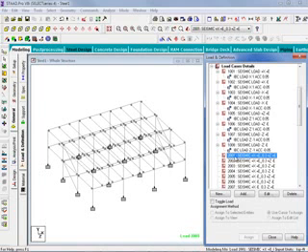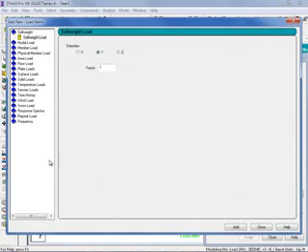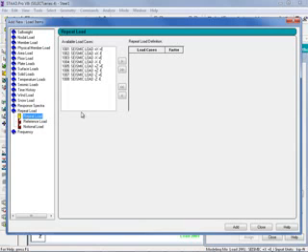We'll click on our 2001 seismic load case and click on the Add button. Now what we're going to be doing is defining a repeat load. So we'll select our repeat load item, and we can see that all of our available load cases are shown here. For this one, we will be adding our seismic load in our x direction with positive eccentricity. I can hold down my control key and also select one of my z load cases, and then I'll click the single right arrow button.